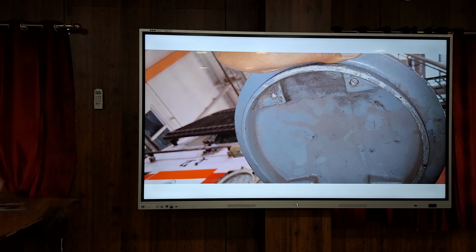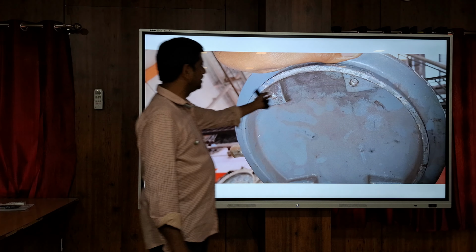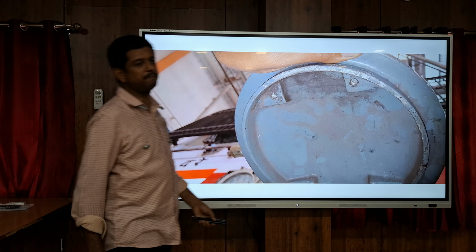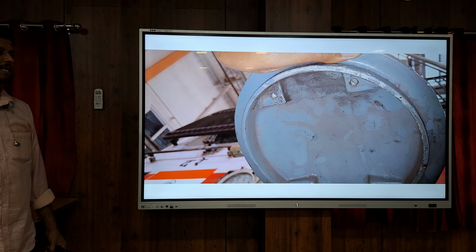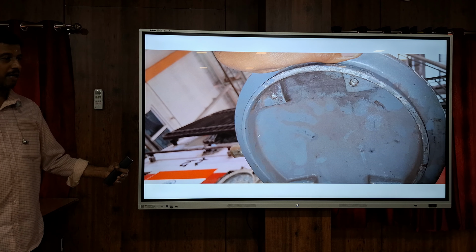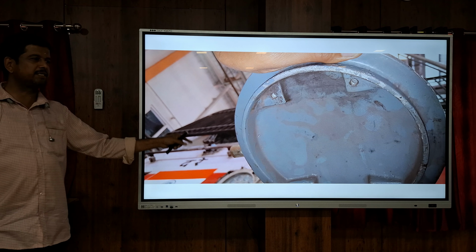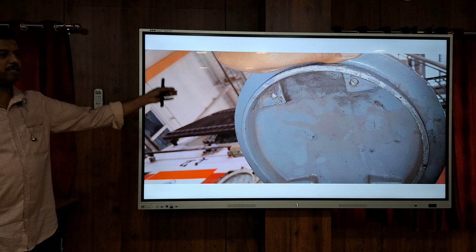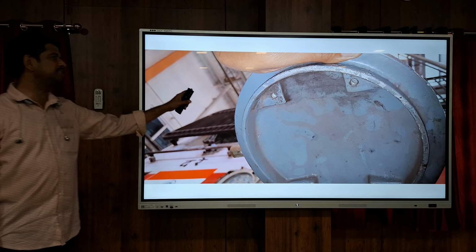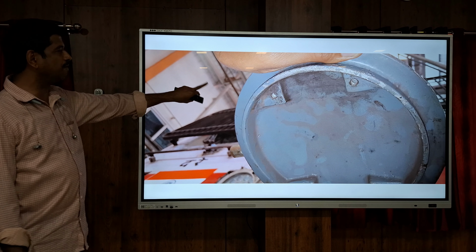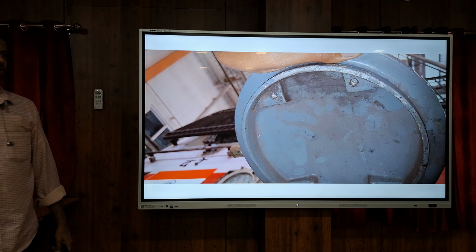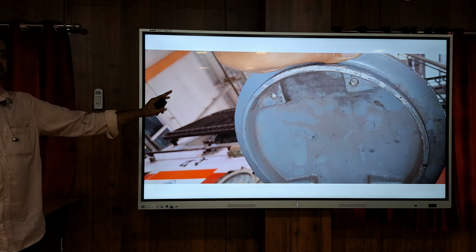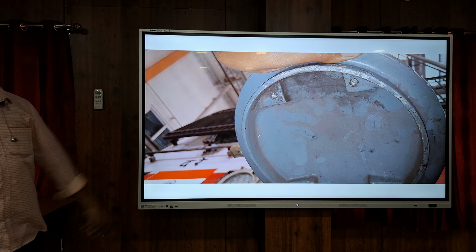This is the IV coupler output connector. Here one link will be there. That link is for shorting pin number 7 and 10 in the coaches. In case they detach the IV coupler, this cover will be closed so that circuit continuity will be available for turning on the contactor. For the loco side, it is not required. And in case any water entry is there in that terminal, that causes an earth fault in the control circuit. So we have removed that terminal, and there is no stagnation of water inside.